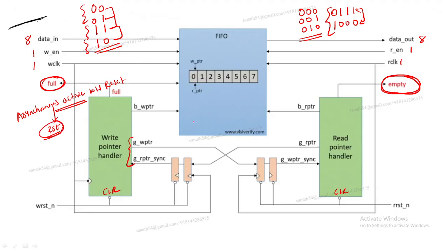Okay, you want to reset your circuit. You can't reset if it is synchronous. That's why reset applied is what we call asynchronous. Reset removal is synchronous only. When it is in functional mode, reset removal is synchronous only, but whenever the reset is applied, that is asynchronous. That we discussed with relation to the D flip flop.